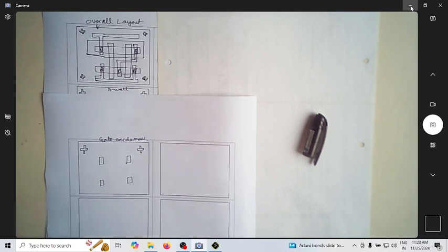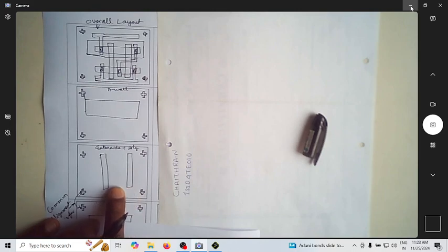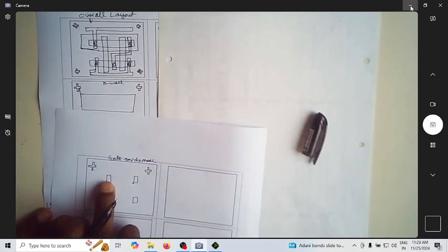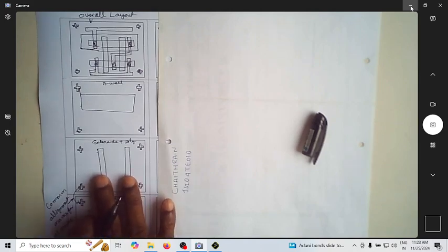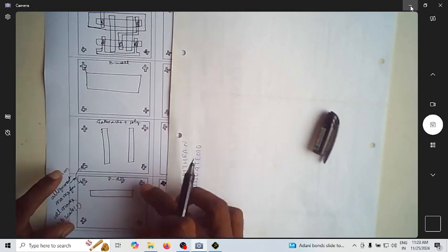This is my gate oxide, and this is my poly mask, that is the gate structure. This is the gate oxide, the thin oxide, and this is my polysilicon gate structure, which is realizing these two. And then I have my P diffusion. For the P diffusion mask, you can see the alignment marks are again identical.